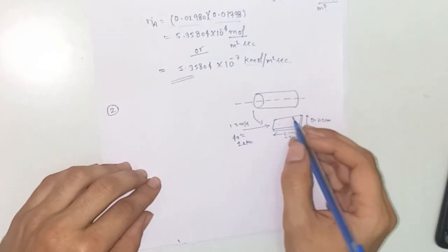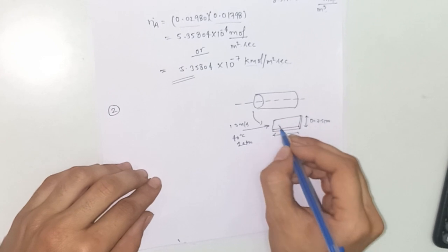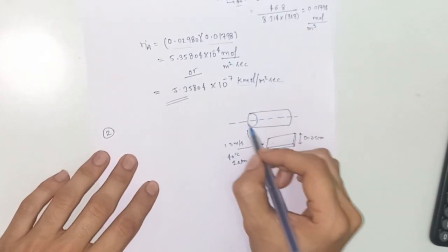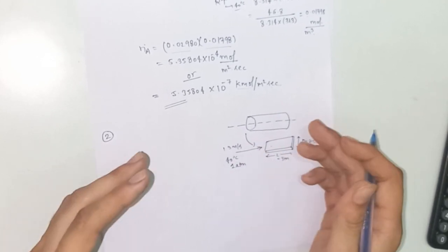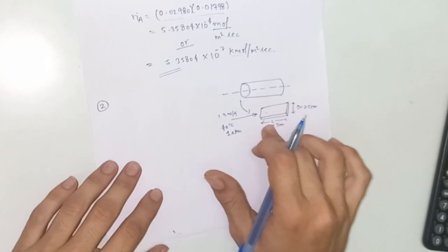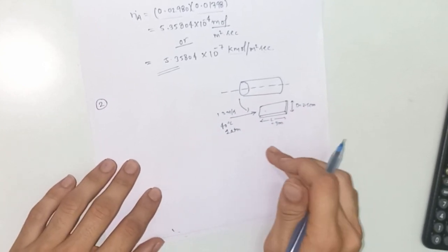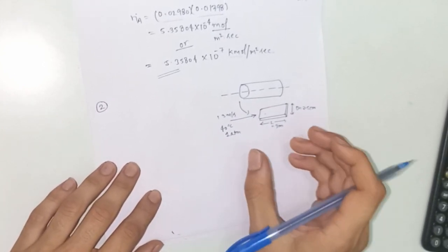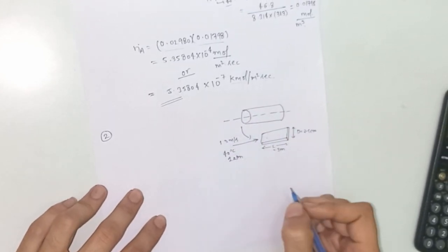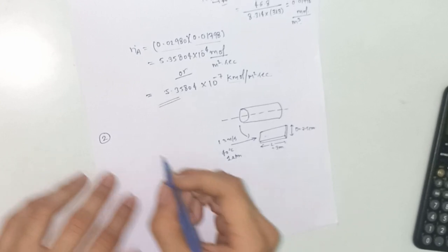So now because we know that the contact area increases, we cannot use the relations of the cylindrical pipe or cylindrical correlations. So now we're going to solve this problem using the Chilton-Colburn analogy and all the formulas of the flat plate. So proceeding with that, first of all we would start with the Reynolds number.